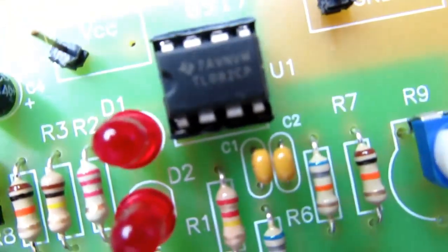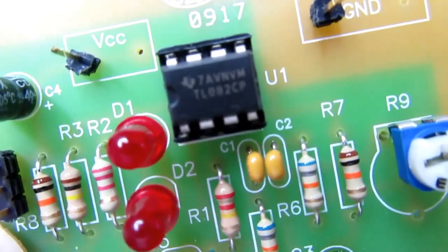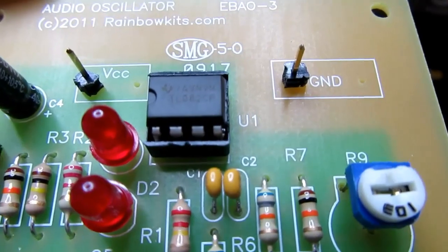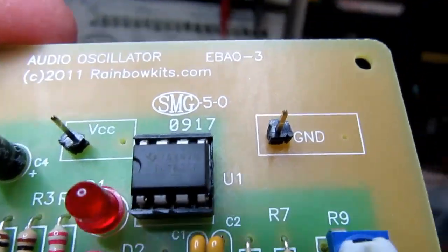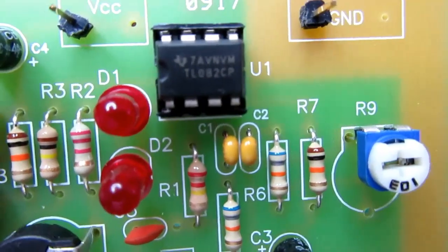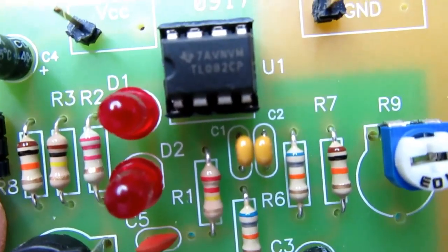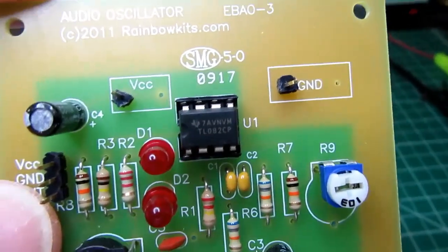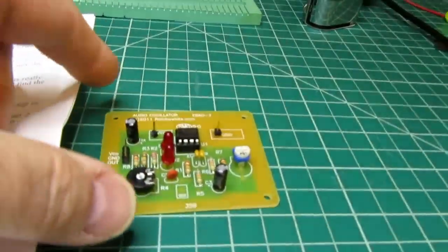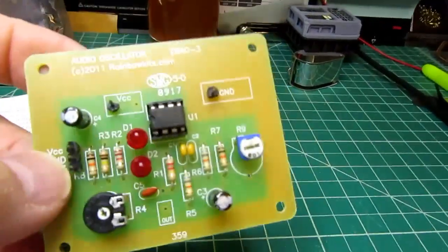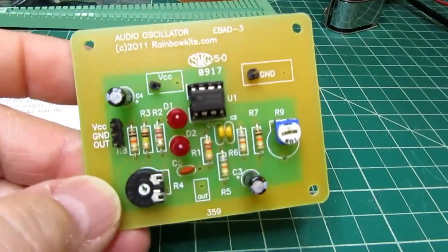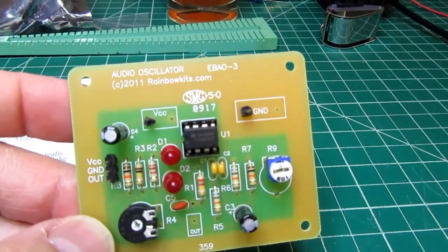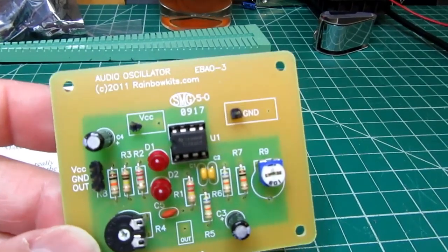It's kind of surprising that a brand name op-amp is used here. It isn't really identified as a 1458, even though the instructions call it a 1458. It's a TL082. Well, that TL082 is not the same as a 1458. I thought it might be Texas Instruments' own part number for the same thing, but it isn't.